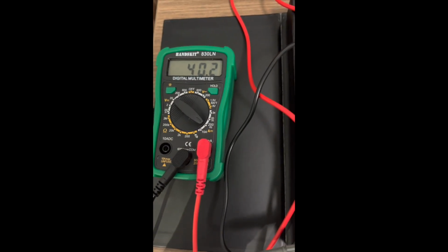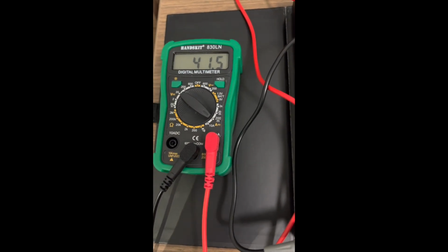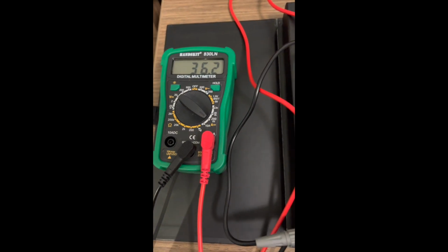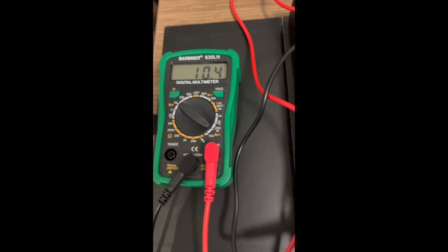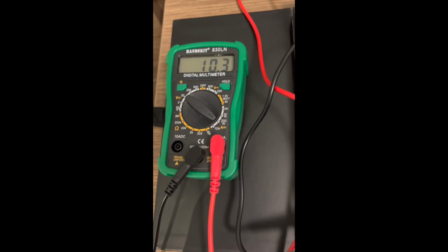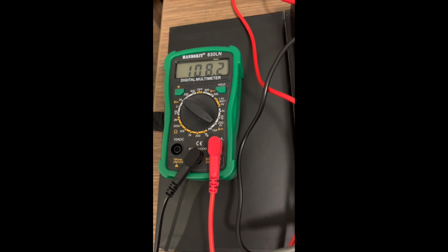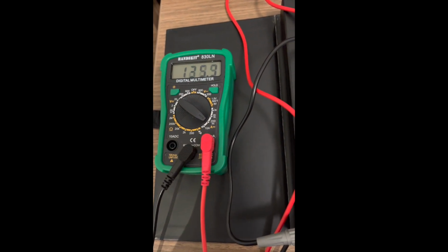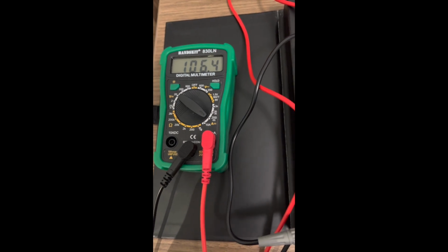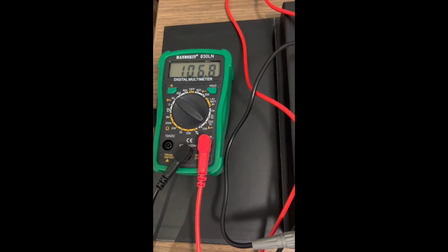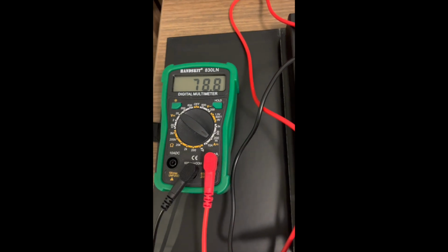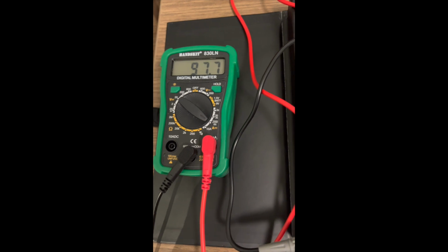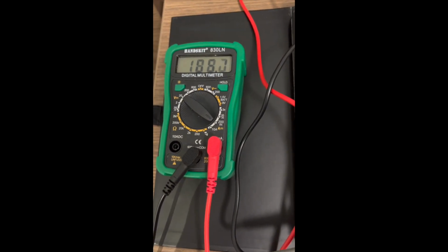I can see it came through to my watch, and it looks like it's hovering around 40 milliamps. Up as high as, I think I've seen 100 in the past. Yep, so we got an initial spike there of 100. On successive requests, it's staying a little bit higher. But it looks like it's ranging somewhere in the range of 40 to 100 milliamps while it is in active state.